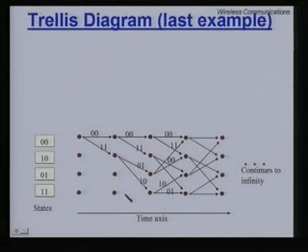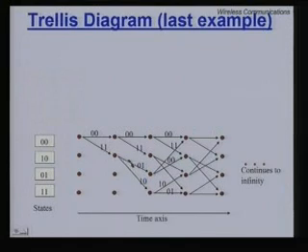Noise is random. So, many times it will appear at the decoder that the transition from 0 0 goes to 1 1 because of the random bit errors. Clearly, you can detect it, and you can also look at what is the most probable transition that you should have been through, thereby correcting the error. So, I have added another dimension of structure.